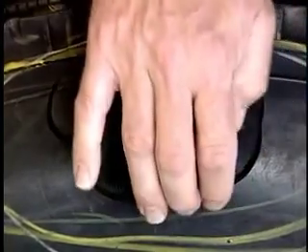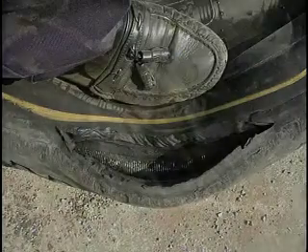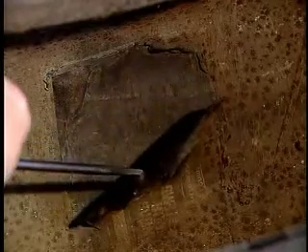Air infiltration occurs when there is damage to the inner liner, allowing the internal air pressure to travel within the steel and other rubber products, causing a separation. Air infiltration can be found in the tire's sidewall, bead area, and crown belt area. The primary causes to look for are nails, bolts, and debris perforating the tire, section or nail hole repair patches, cracking, splitting, or lifting. Tire bead and liner damage can be caused by improper tire mounting procedures.